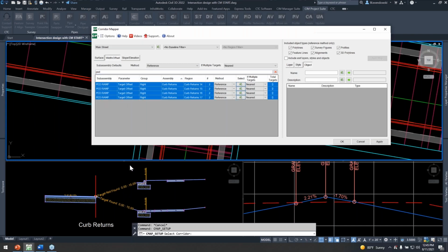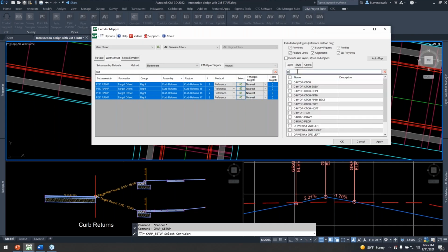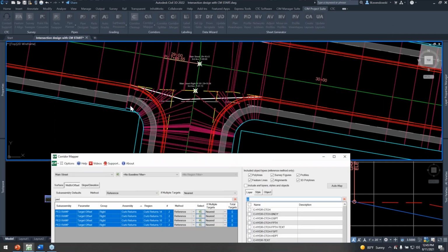And again, these are the conditional subassemblies, and they're named the same, and so we see actually 2 instances of this one for a particular region. So there's 8 different subassembly instances. We'll grab here. This one we're going to go to layer because I've got some simple polylines drawn there that are going to trigger where the drop curve should go.